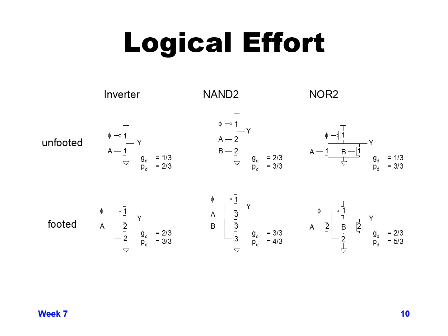Now, if you go back and compare these values to regular static CMOS for each of these stages, you'll see that the domino design is better in all cases, even though the footed version is obviously not quite as fast as the unfooted version. It's still better than a regular static CMOS gate of the same type.